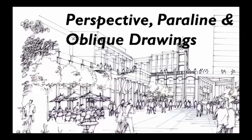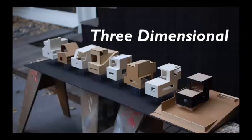Paraline views are also three-dimensional views but represented on a two-dimensional sheet. And oblique drawings are more similar to elevational views in that some of the surfaces are projected flat or perpendicular from the surface of the building in the drawing, but the things that are going away from us at an angle are shown in perspective.